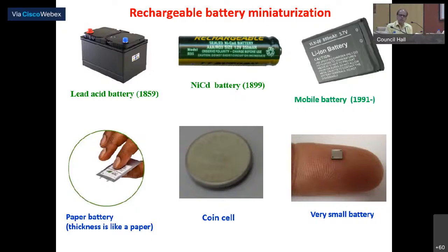Here, materials chemistry teaches you which kind of casing should be used. Coin cell is using SS casing, whereas implantable batteries cannot use SS casing. We can discuss these things afterwards. For implantable batteries, one uses titanium casing because titanium is more compatible with body fluids. So materials chemistry teaches you the concepts of compatibility. All these things will be taught to you in this course.